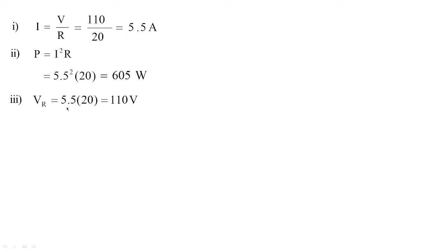Okay, once we are done with the resistive voltage, let us estimate the inductive voltage as well as the capacitive voltage. So the inductive voltage is given by I into XL. XL is the inductive reactance multiplied with the current will give us the value of the inductive voltage. Then what is XL? XL is the inductive reactance which is given by 2 pi F naught L.